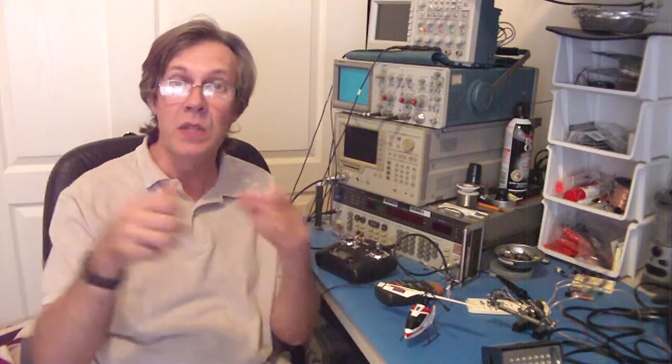And you could look at the film and see the frames and see this is an instant of what happened at that frame time, and then the next frame was what happened after some delay at the next time. Now what was not recorded was what happened in between those frames. And so that's the difference between continuous time, which is the world we live in, and discrete sampled time, which is what we have in digital systems and in things like movies.